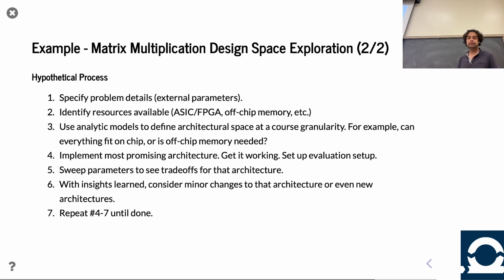Then maybe you will use some analytic models to help you with the modeling a little bit, right? You can do things like back-of-the-envelope math: okay, I want to reach a certain throughput. I know how many math operations I need to do to reach that throughput. Can I fit enough of those hardware components on the chip, right? You don't need to write Chisel to figure that out. You need to do some back-end math, maybe with a spreadsheet, and see, wait a second, am I going to fit everything on chip? Am I going to hold enough SRAM to hold the matrix on chip? If yes, great. If not, I'm doing off-chip memory.